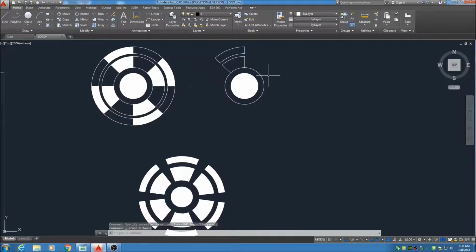There we go. So when I did this, first thing I have to do, one more thing, I have to trim this out. So I have these individual shapes that I made, and I went and used this tool. This is called the polar array right here. You select it, and it says select your object. So I'm going to go ahead and select these two objects, and then hit the space bar. Needs a second here. It wants the base point now. So I'm going to float over the center of this like a pinwheel.